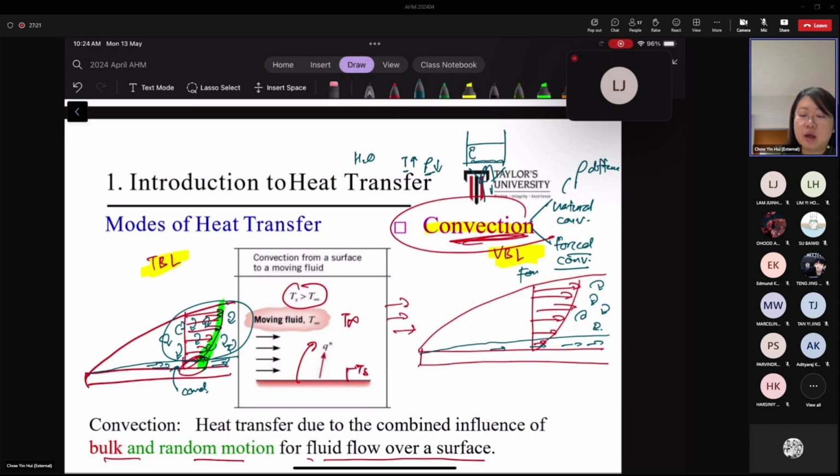But the water in the upper region is at a lower temperature and its density is higher, so it will sink to the bottom. When the heating is continuous, more water is heated and its density decreases, so it travels up, while the cooler water sinks to the bottom. In this way, it creates motion of the fluid.